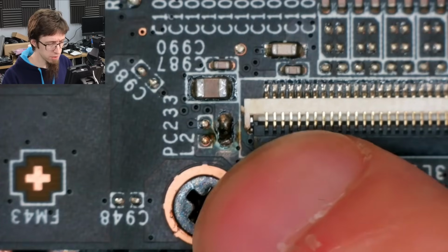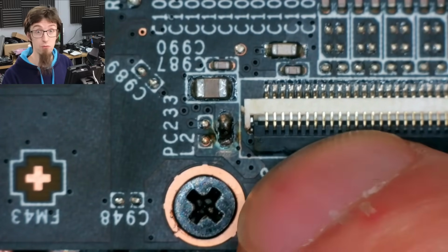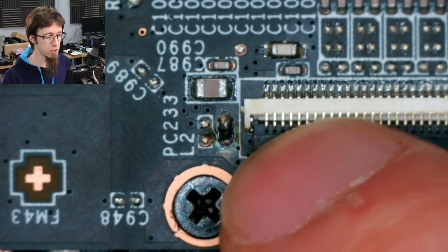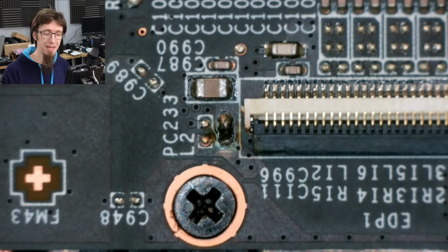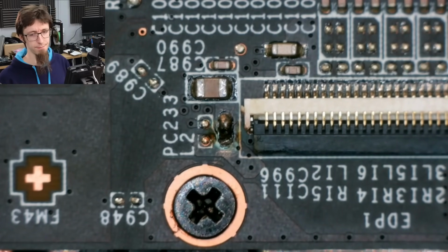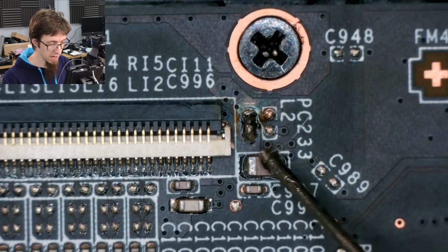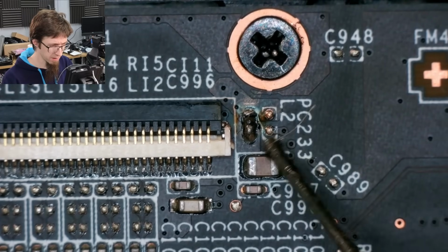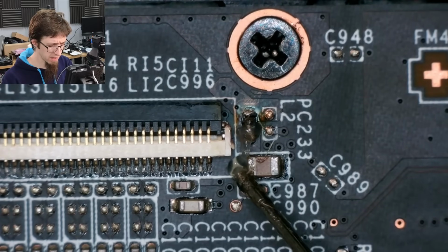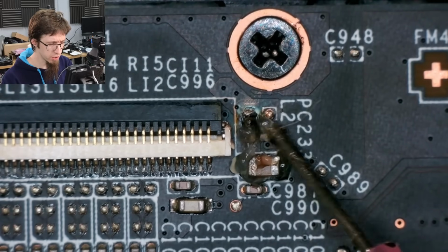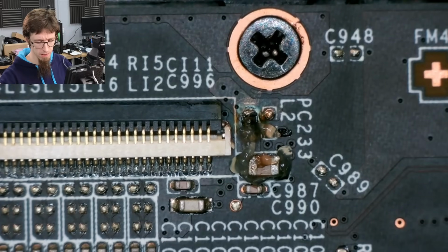Now we're really close up to this display connector and I really don't want to damage that, so we're going to try and do this with no hot air. So I might be a little bit janky while I'm trying to be a soldering iron hero, but here goes nothing. Right, I've just turned the laptop around just so I've got better access with my right hand without clipping that display connector. And I'm just going to flux up that area and just wet the joins just so things come off a little bit easier.